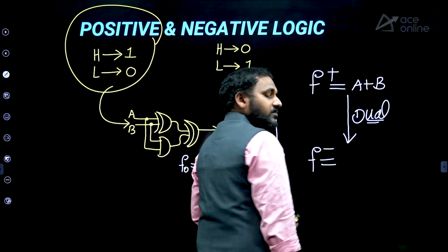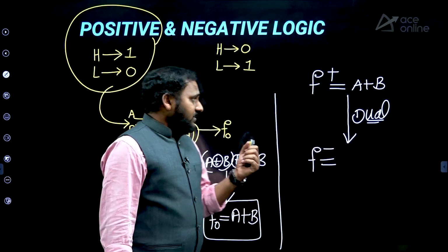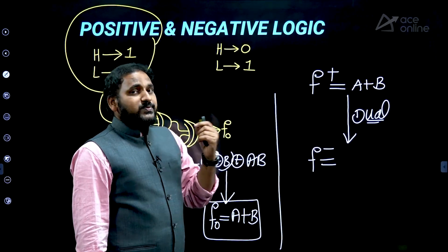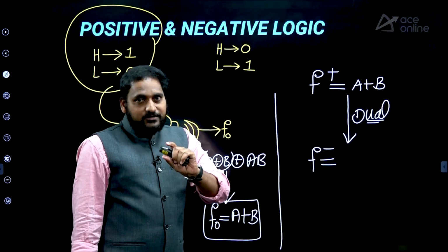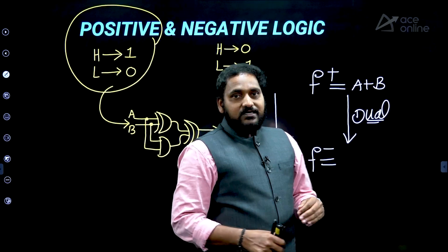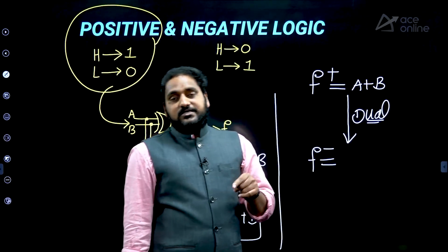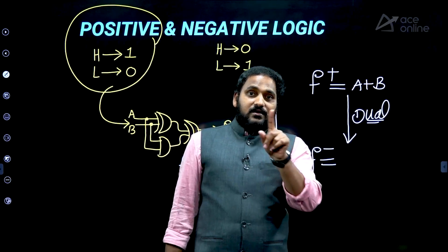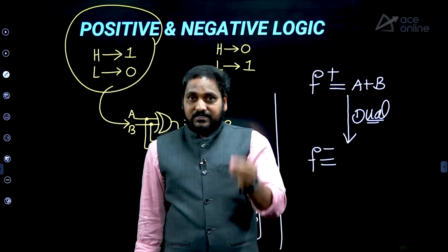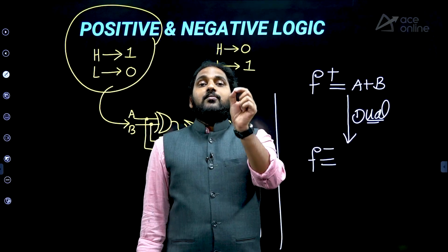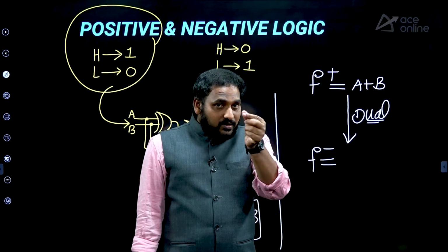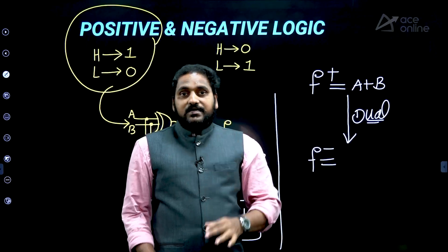What is the duality? Do you remember? These are very fundamental things, so I need to increase the speed slowly. Be ready to catch the speed. Duality and complement, two things we have discussed. Duality is obtained by interchanging ones and zeros and OR and AND operations. Literals should be as they are. Complement is a little different: ones and zeros interchange and OR and AND operations interchange, but literals have to be complemented. In duality, literals should be written as they are. Do not change the literal.